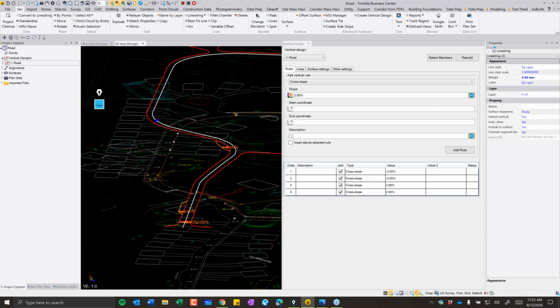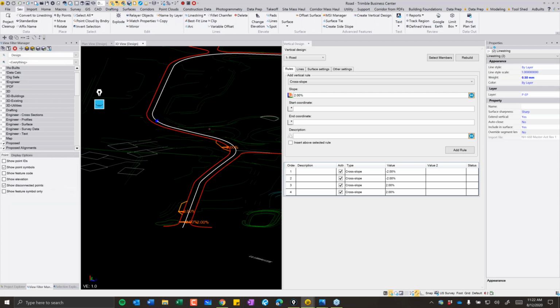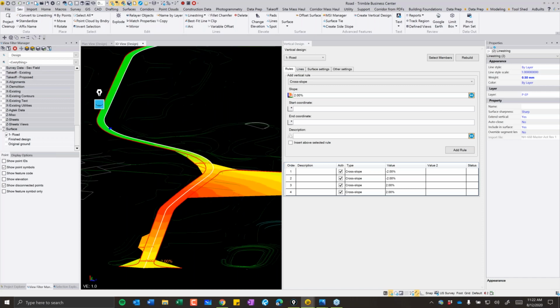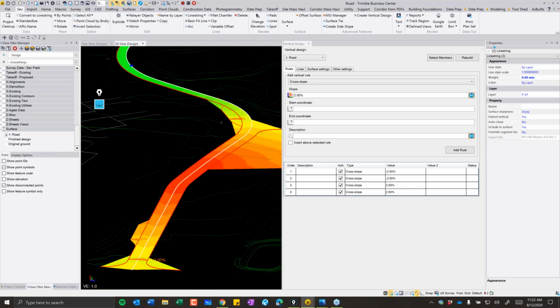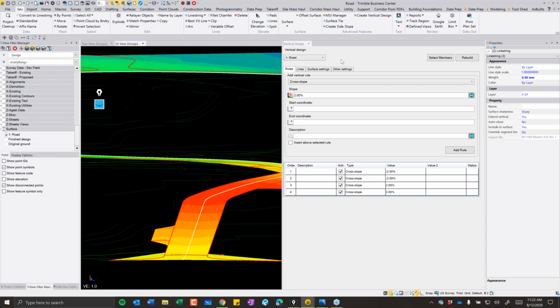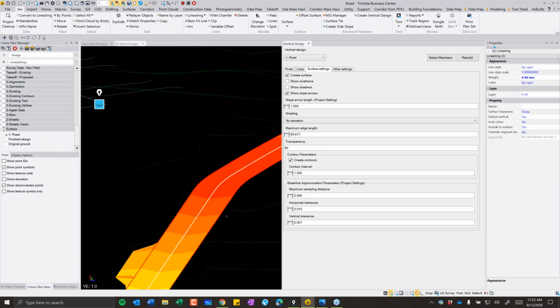So could you show us the surface and the contours as well there at that point? Like as you're building a surface, you're building line work here that is actually building a surface in the background, right? Or are you not building a surface here? Correct. It is. Sometimes I'll turn off the surface because I find it's a little faster, and because I build things segmented, it's not always true to what the final surface is going to look like. But the advantage of this is you can go into your surface settings and have it create the surface if you were to combine everything.